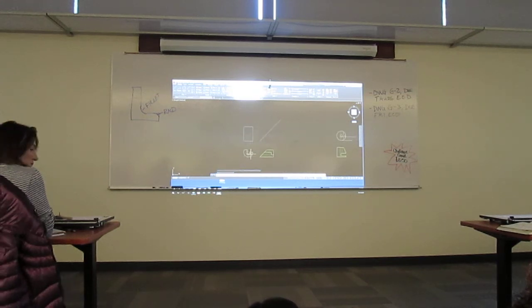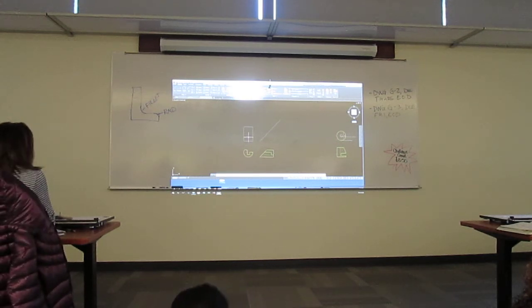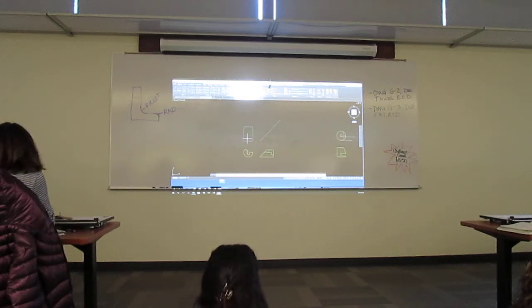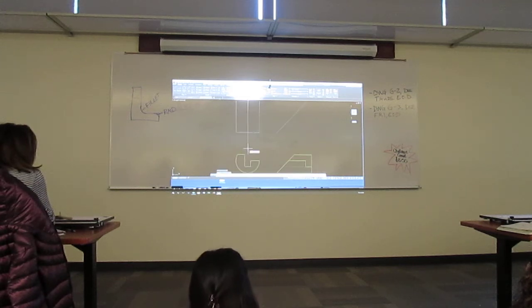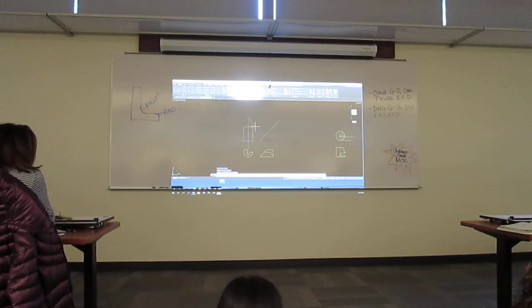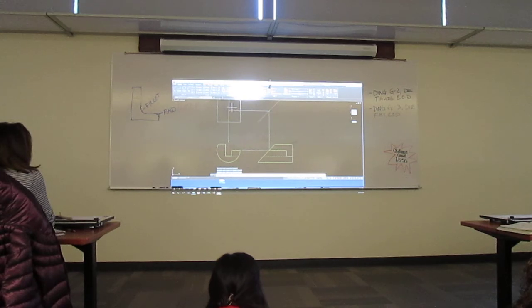Now, I know that this is a circle right here, and it's going to appear as a circle up here, so I need to locate that center point. Okay, when I do circles, you need center and radius, right, to draw them. So I'll bring up first the center point. I know it is right here. Then let's bring the center point on the right side view. Remember, it occurs right here. So here's the center. I'll bring that up, bring that over. There's the center point of my circle.